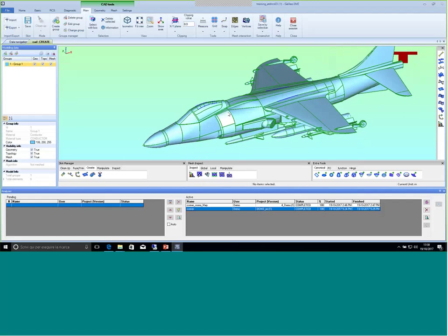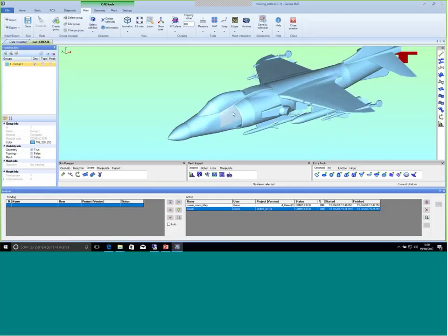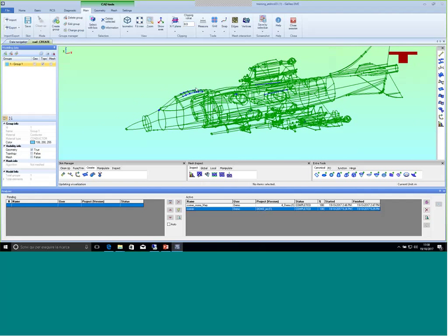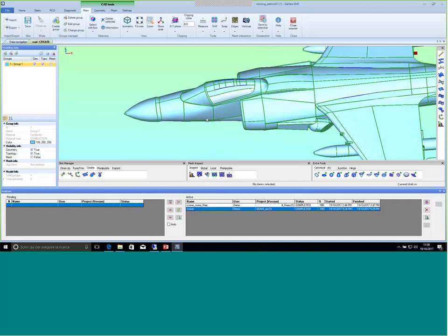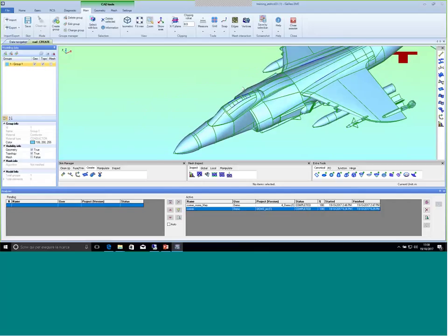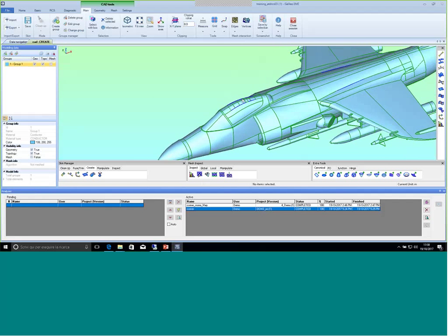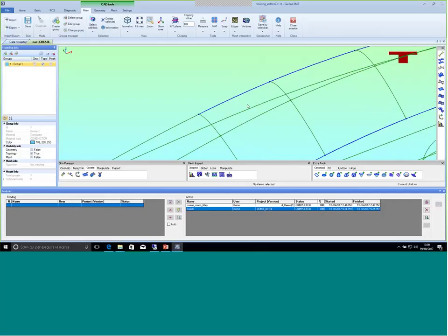Here we have three levels of representation. We have the geometry, that are the mathematical surfaces that are describing my model, and we also have the topology. So when we have the topology, it means that we have all the connections between all the patches, and all the connections that I realize here in the geometry will be constraints for the mesh model. In this case, for example, I have two different edges that are very close to each other, but still two.